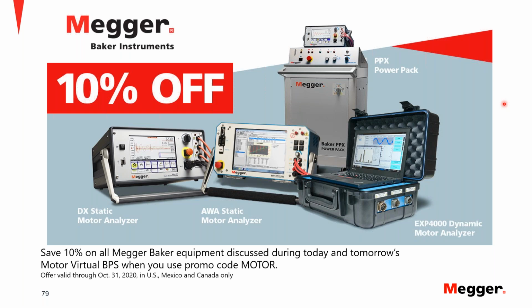Of course I would need to see the power, and then I may need to tell you that our machine, the DAS, I don't know, the 14 kV that you need is not enough. Maybe we need to go higher in voltage, because machines that go higher in voltage are also capable of testing machines that have higher power or larger frames, or bigger capacitances.